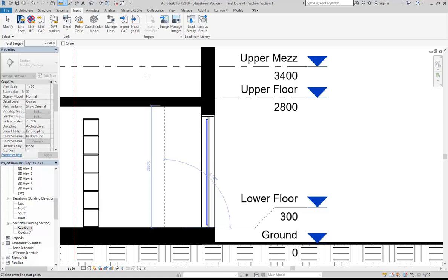Don't you know the height, the minimum height for a ceiling in a living space? No, 2400, yeah. So 2100's for service spaces, kitchens, bathrooms, things like that. Can be 2100. But again, living spaces, yeah, you're right, 2400 is the minimum. So this is an existing building though, and the ceilings are already lower than that. So that's the height we need to make them. So we're making them lower than what's allowed, but again, because it's existing, we can say that's okay.